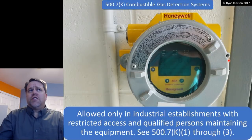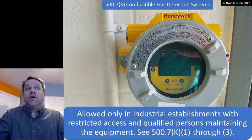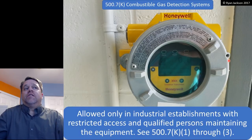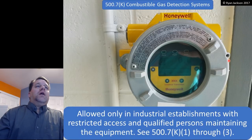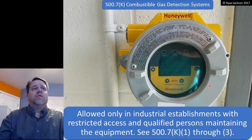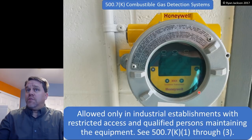The last protection, actually not quite the last protection technique, item K, combustible gas detection, are only allowed in industrial establishments with restricted access and qualified persons maintaining the equipment. So there's a lot of criteria in order to use a combustible gas detection system, but they're quite good. They show the lower flammable limit or lower explosive limit, and they will set off an alarm letting you know that the lower limit has been exceeded.